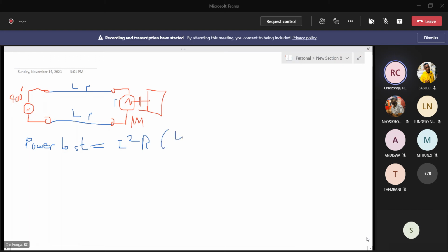This is what gives you the loss of power. This is not a stove, it's not a heater. You are sending power to the motor to drive a mechanical load. But because current flows in a conductor and in the wires of the motor, unavoidably you are going to generate heat, represented by the current squared times the resistance. So that is the basic thing that you must know.